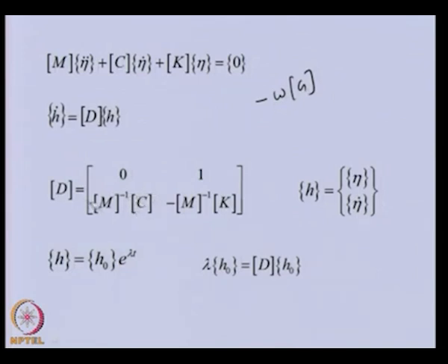So, this will become positive, omega will not be there, and c. Now c is a damping matrix, it is not the gyroscopic matrix, and we now expect the eigenvalue to be complex, and even the eigenvector to be complex in this particular case.